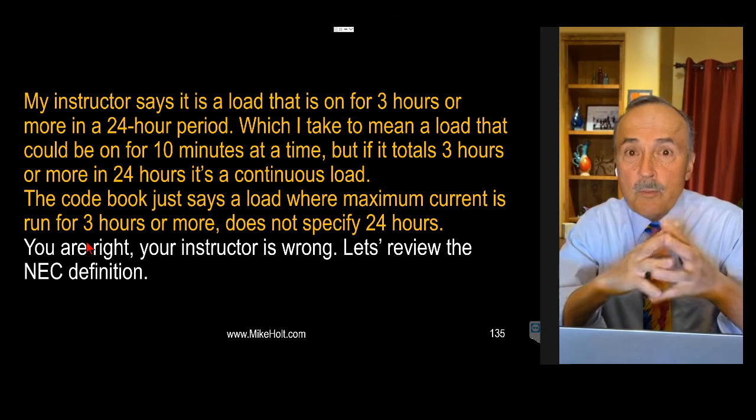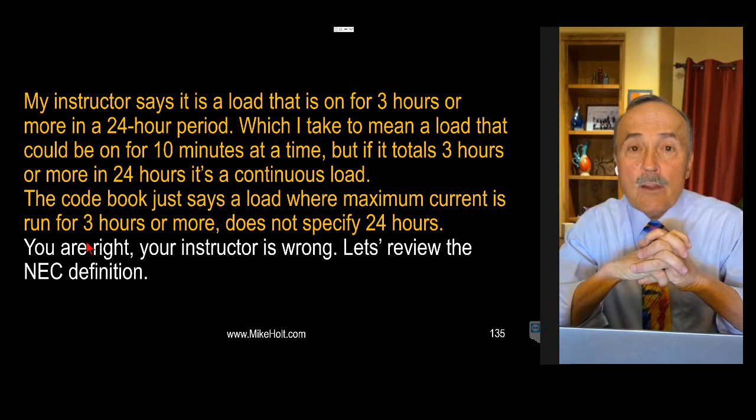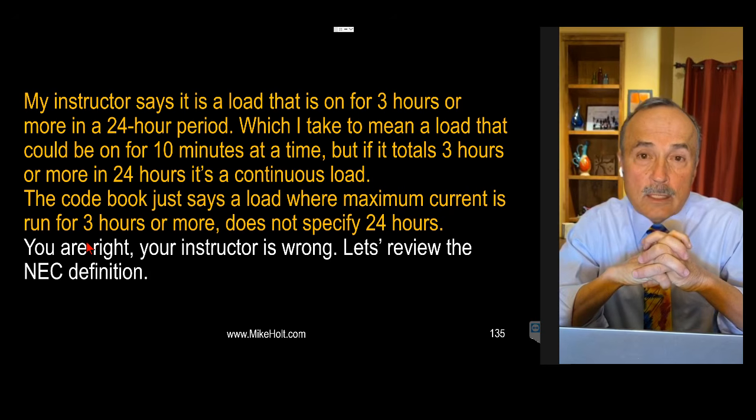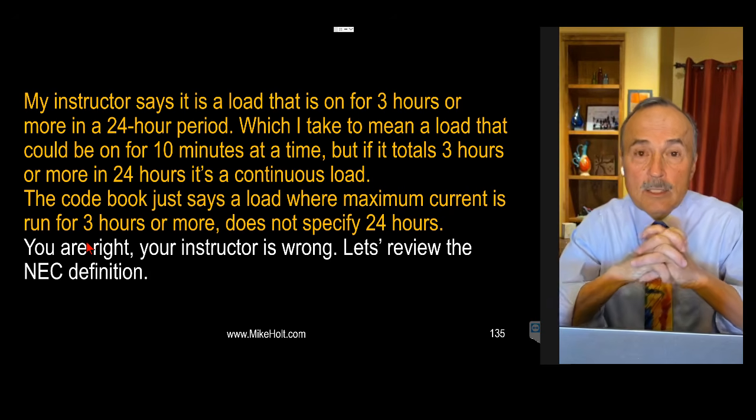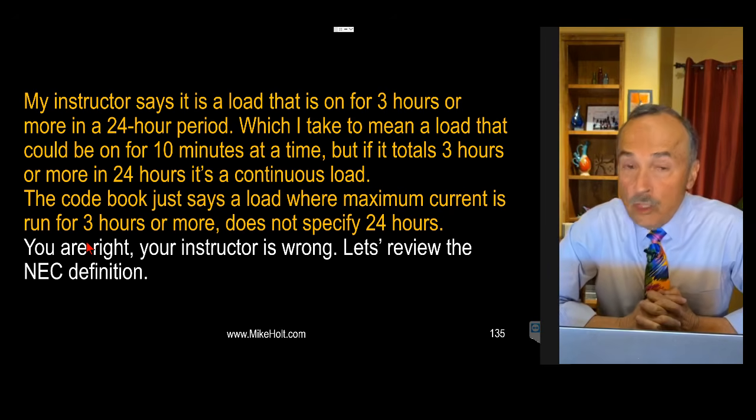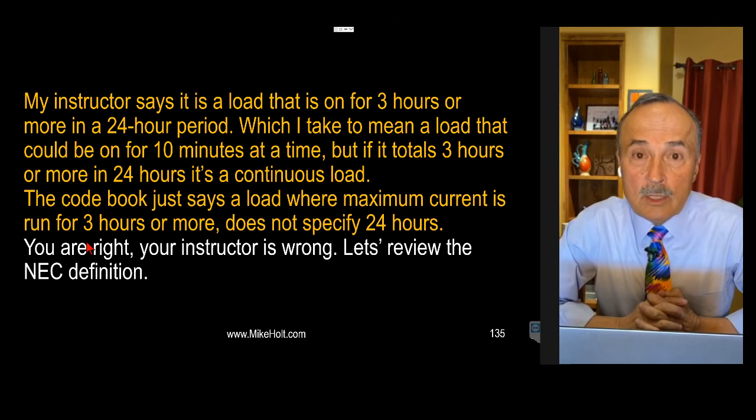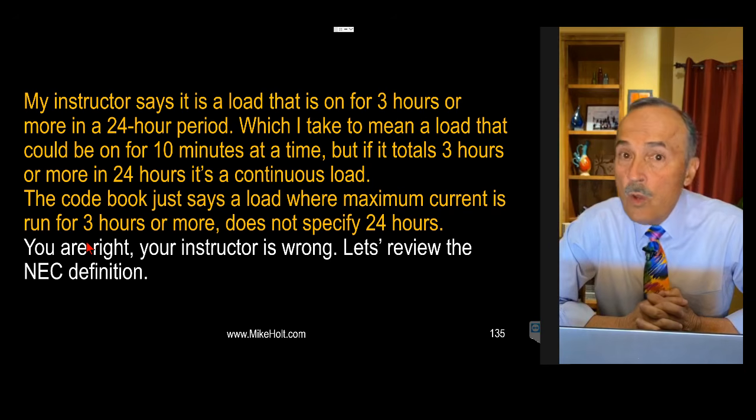Just so you know, circuit breakers are not rated to take current for 3 hours or more at its rating. Let me explain this to you. 100 amp breaker. You can put 100 amps on here as long as you don't run it continuously on it. If you run it for 3 hours or more, the breaker is not designed for that application. It's designed for an application where you don't run it for 3 hours or more.